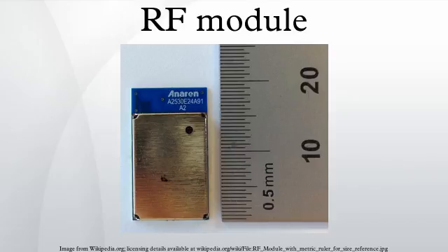Transmitter modules. An RF transmitter module is a small PCB sub-assembly capable of transmitting a radio wave and modulating that wave to carry data. Transmitter modules are usually implemented alongside a microcontroller which will provide data to the module which can be transmitted. RF transmitters are usually subject to regulatory requirements which dictate the maximum allowable transmitter power output, harmonics, and band edge requirements.